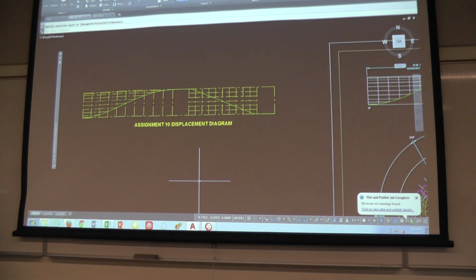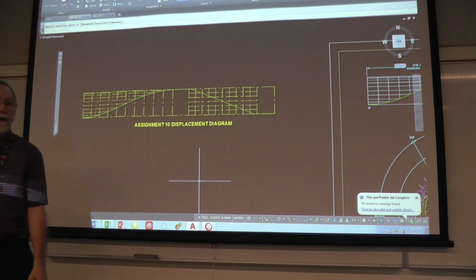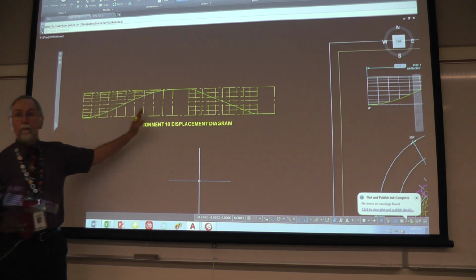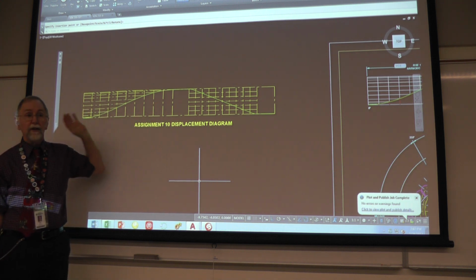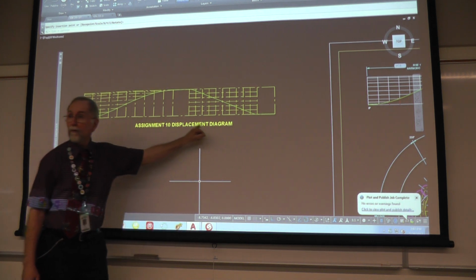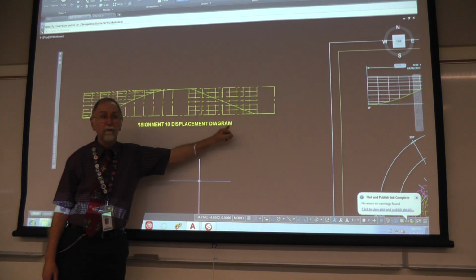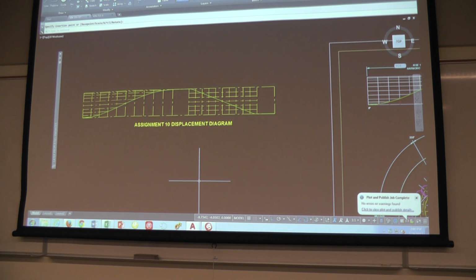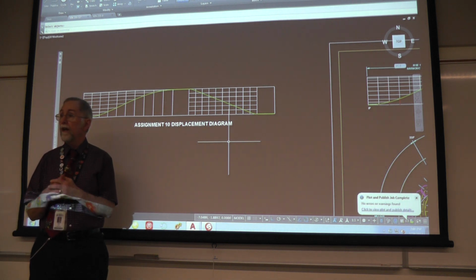So it's going to have some funny line types and line weights and all that kind of stuff. It is a block at this point. You need to explode it in order to get rid of this verbiage right here. All this is just verifying that this is the drawing that you're going to start with. X enter is explode in AutoCAD. Once you explode it, it will go back to the layers and the line types that it was created as.